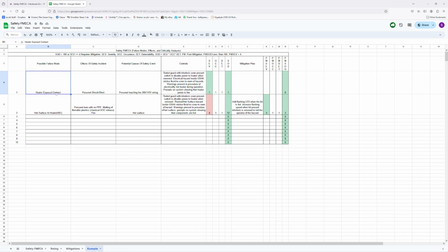So basically, what if you had, and it happened on a project that I'm still currently working on, but early on in this project, there's a tiny little exposure of a bare metal contact that we have 208 live voltage coming to on this heater. And so we need to make sure that personnel cannot touch that and then touch something else.